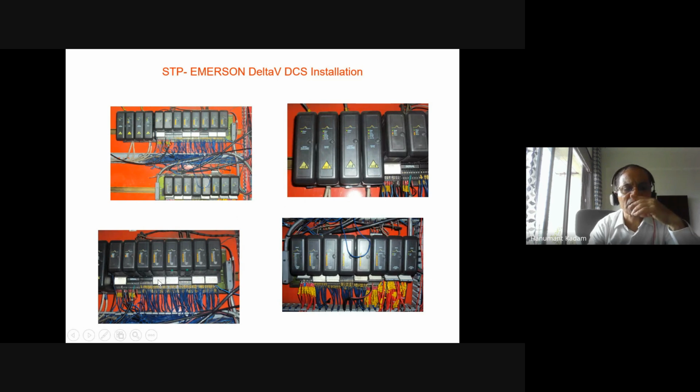So actually this is the system. You can see here it is also mentioned the cables are there. Power supply cables on top. This 24 volt DC power is redundant. Here also redundant power is there. So it is on the back plane of the carriers. So this is what the system is. What you can see in the picture: power connections, network connections, and IO connections, and how it is extended in the Delta V system.